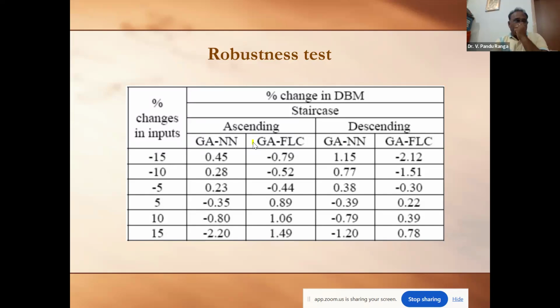Sometimes the noise levels are high over long usage of the sensors, and then your gait planner will get a huge variation in the inputs, that is, the foot placements. How will the gait planner react, and will it be able to provide a feasible gait to the robot or not?